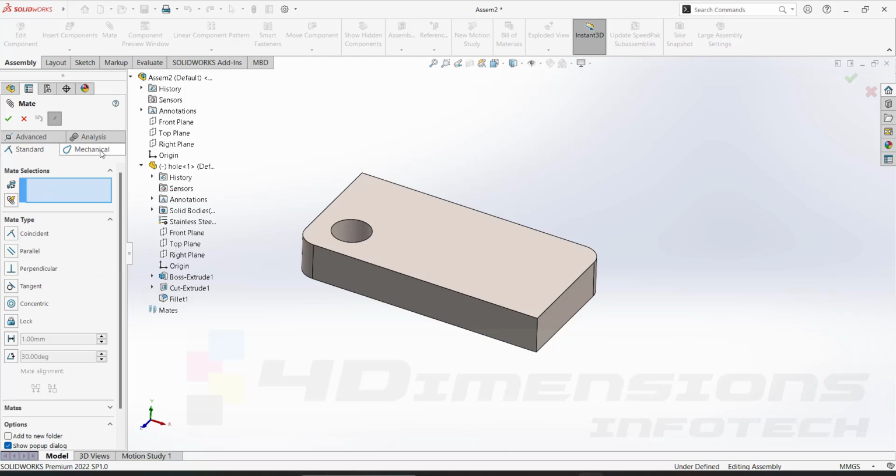So to start with mates, today we are going to start with standard mates. In standard mates, there are a total of 8 types given here. First one is coincide, second parallel, third perpendicular, then tangent, concentric, lock, second last with numerical value, that is distance mate, and the last one is angle mate. The last two mates will have numerical values so as to apply the required mate.